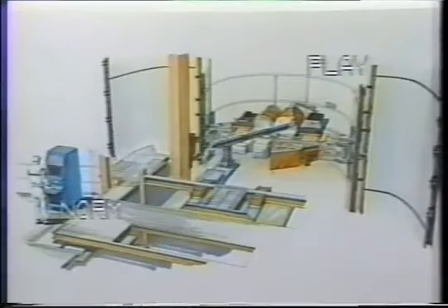The Payload Inspection and Processing System is under development for pre-launch inspection of the Shuttle Bay at NASA Kennedy Space Center. This videotape demonstrates follow-the-leader control of prototype hardware for snake-like obstacle avoidance. Given an obstacle-free trajectory for the manipulator tip, the follow-the-leader algorithm ensures whole-arm collision avoidance by forcing each link to follow the tip. The system is programmed offline by teleoperation. It also accepts trajectories from path planners. Offline computer graphics software is used to validate motion prior to operating the hardware.